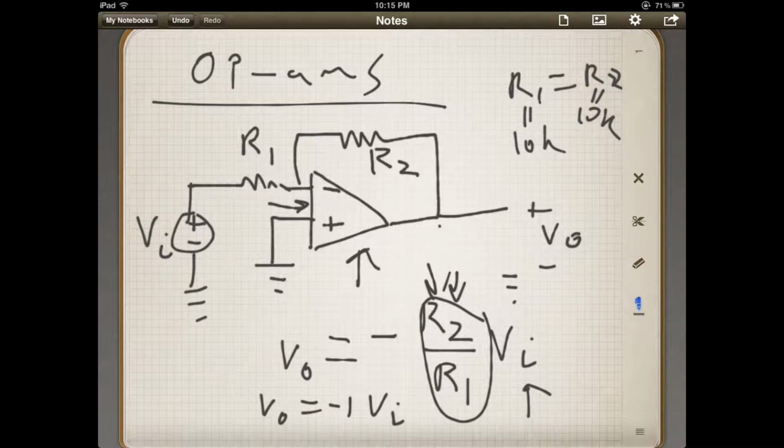You don't want your currents to be anywhere close to the operating currents of the IC, because otherwise it'll skew your results. You might have numbers acting wacky on you. So definitely stay in the high kilo-ohm resistor range when you're choosing your resistors. But pretty much anything goes.